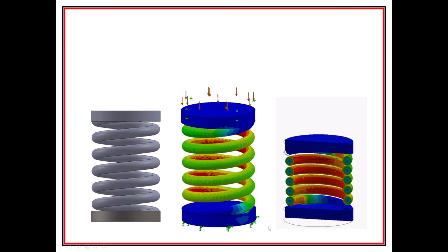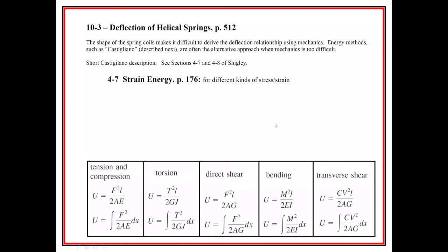You see right there, you can see that it's got all that stress on the inside, maximum right there. All right, so the other thing we care about in springs, one of the purposes of our springs is to get some deflection, right? And we want to know the relationship between force and deflection, and that is our spring rate. And what we do is we use strain energy as the concept, because that's one of the things that springs are. They store energy.